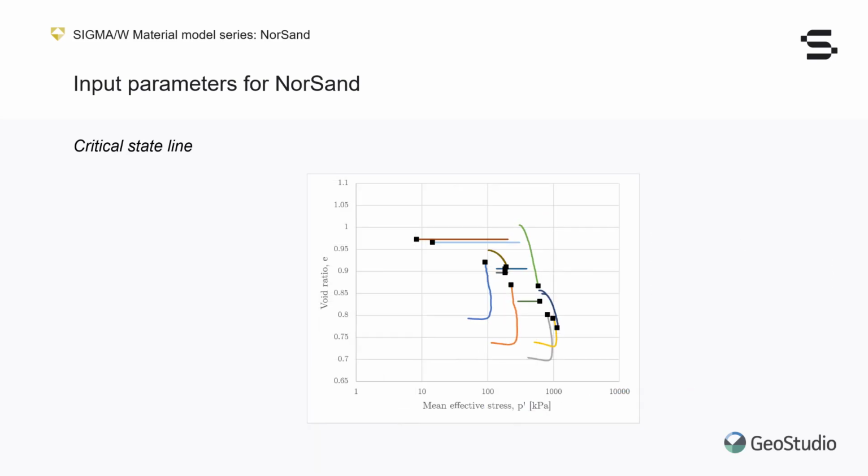We should expect that this blue curve would still need to experience some level of deformation before it really reaches its critical state. In this case, this would mean that its void ratio should continue to increase. We should do a similar exercise of cautious judgment for each end of test before attempting to place the critical state line. Assuming that the critical state line would be straight in this void ratio, log of mean effective stress plot, would yield the following best fit.